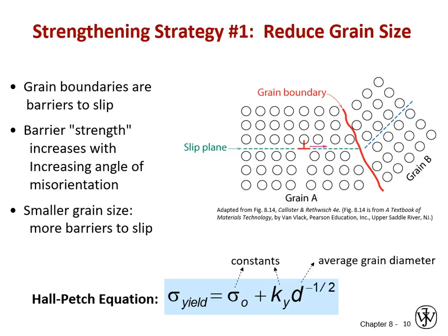So again, it's important to remember that the smaller the grain, the higher the yield stress. And this just means no grain within the material can deform as much until the dislocations hit a grain boundary, and that literally limits the amount of slip that each grain can undergo before the dislocations say, hey, give me more stress if you want me to move to the next grain.